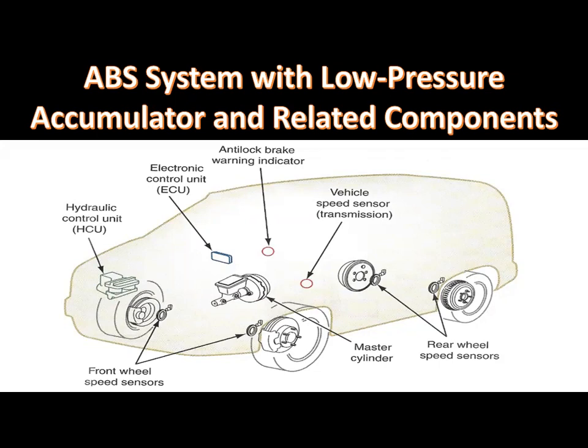During a brake application, if a wheel speed sensor signal indicates to the control module that a wheel is quickly approaching a lock-up condition, the module closes the normally open solenoid connected to the wheel caliper. This action prevents any further increase in fluid pressure to the wheel caliper.